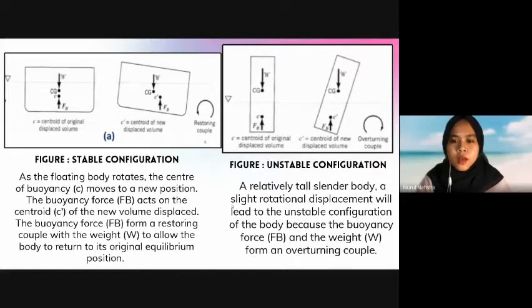Meanwhile, if the body is relatively tall and slender, a slight rotational displacement will cause unstable configuration of the body because the buoyancy force and the weight form overturning couple.